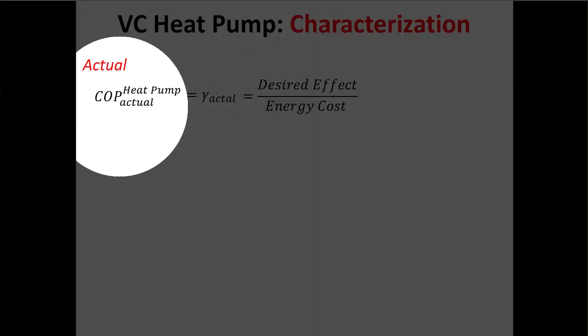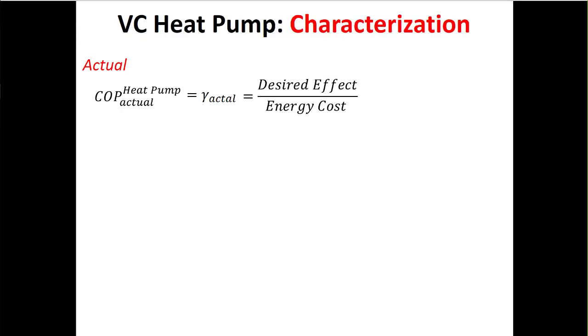But if you just want to say COP, subscript heat pump, or something like that, that's fine, right? It doesn't really matter the variable name that you use here. It doesn't even really matter conceptually if you're talking about a thermal efficiency or a coefficient of performance. All of these things are energy benefit divided by energy cost, right? So here in the heat pump, the energy benefit switched from the refrigerator. So now instead of Q dot on the cold side, it's Q dot on the hot side, because we use these heat pumps to heat up the hot place. But the energy cost is still the same.